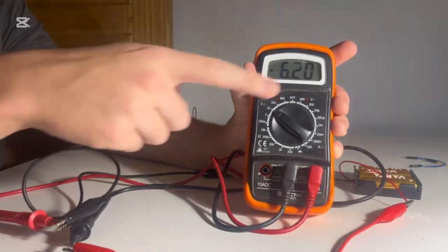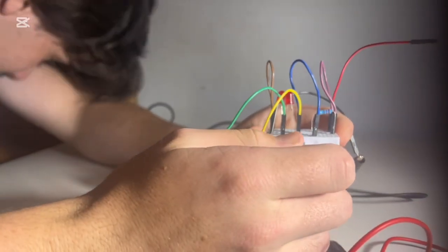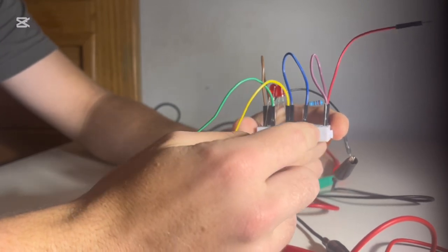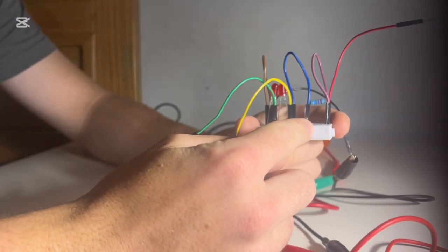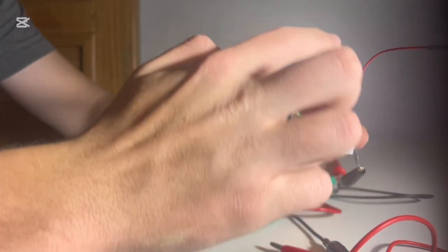Now reposition the voltmeter to sit in parallel across the first LED. Check that you have wired the circuit correctly. That is, all components sit next to each other in a loop with separate branches on either side of the first LED containing the voltmeter.